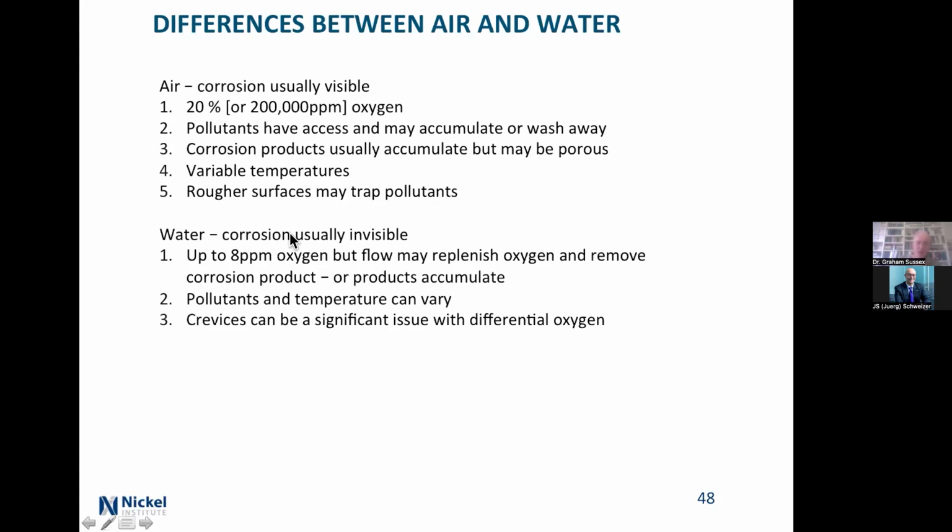Corrosion underwater, you usually don't see it. I mean, it's down there. You might once it's gone on for a while. You have about 8 parts per million of oxygen saturated if you're talking about ambient temperatures, but it doesn't get used up unless it's closed. So if you've got a flowing pipe, then more oxygen will keep coming. The flow may be good enough to remove the corrosion product, but usually it doesn't.